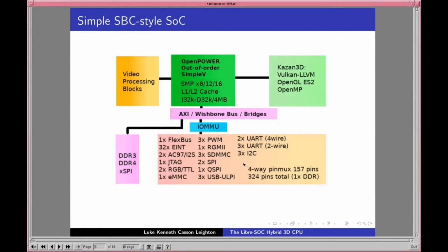This is just a typical chip, 2.5 to 5 watts. It can be a ceramic package or a plastic package, no heatsink needed, and it's extremely compact. If you use miniature components, you can get away with about a 30 by 40 millimeter PCB for the entire design, including power management, the processor, and NAND flash and memory, which will be 3D stacked.